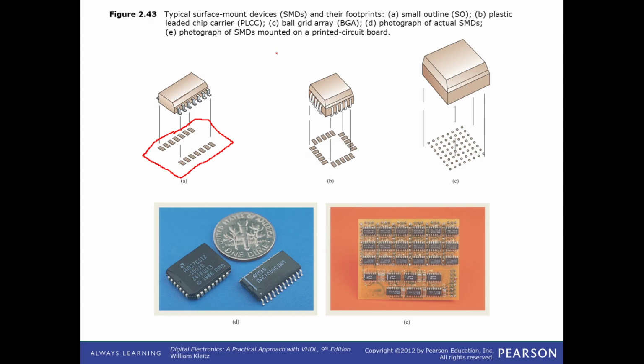Second, here we have the PLCC, plastic leaded chip carrier. It's got these little wrap-around legs that extend a little bit underneath the chip too. You can kind of see there. We place these on similar metal pads, and then we solder those little legs to those metal pads. And these contacts go all the way around the chip, as you can see. It's on all four sides.